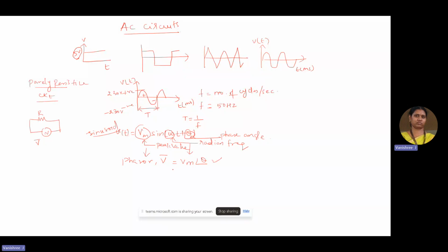Or in other words, we can say that the polar representation of a complex number can also be called a phasor. While we had been discussing about the DC, we were handling the real numbers. Henceforth, since we are going to involve both the reactive elements like inductor and capacitor in the calculation, no more are we going to have the real values alone.